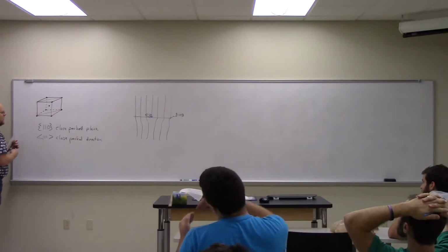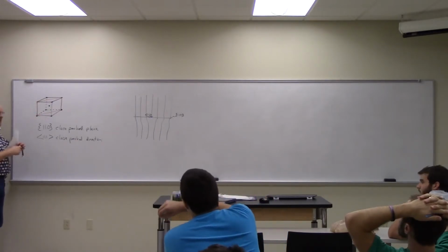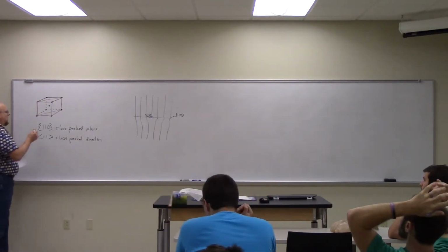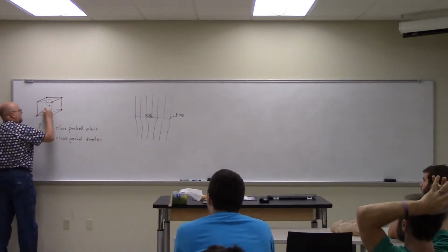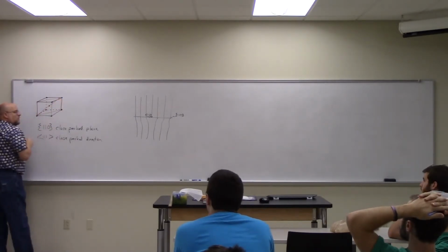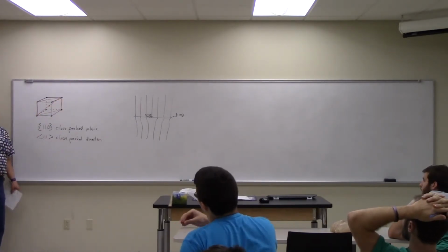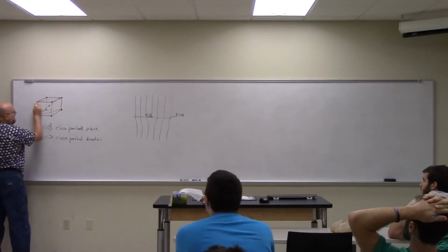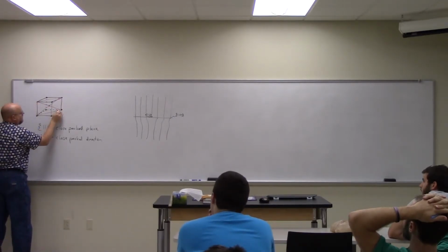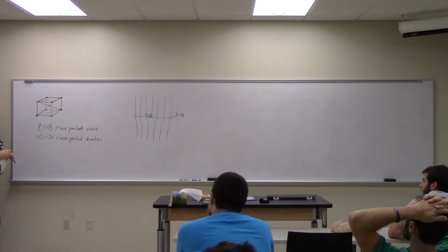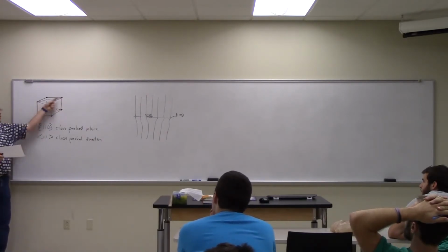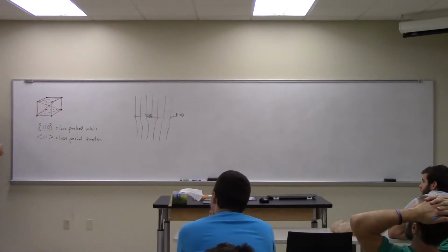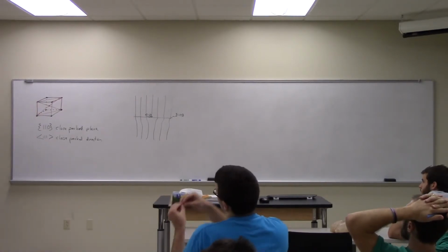So if you look at the picture here, you see that's the 110 plane. The 111 direction in that plane is this body diagonal, or it could be this body diagonal. Right? I could deform it along that plane, in that direction or in that direction, with an equal amount of energy or force.